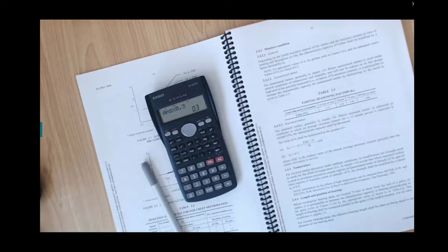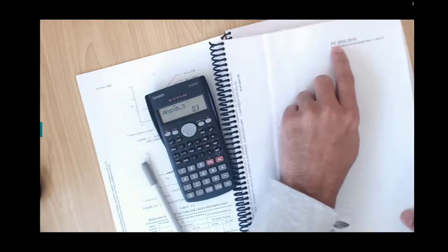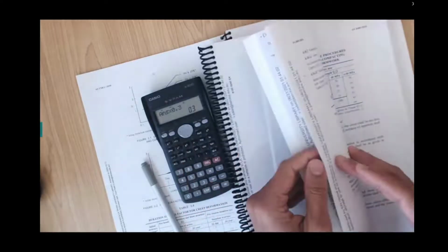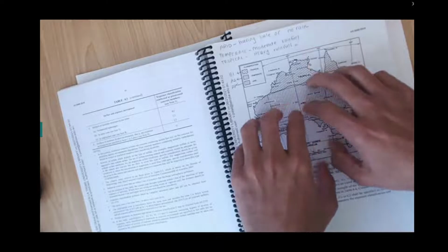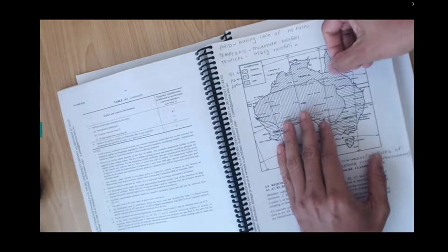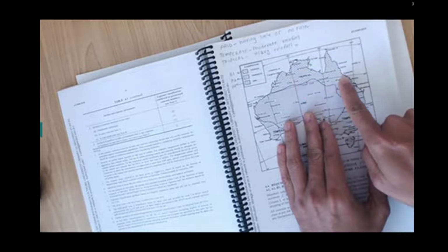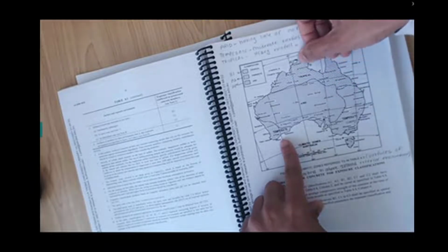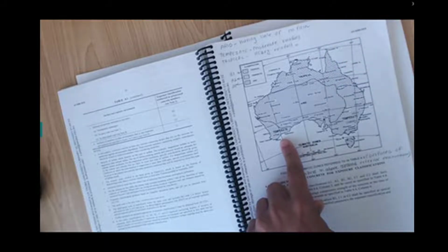But in case this is not the case, look, this is for your explanation only, because this other standard, which is AS3600, has given you these figures there. Probably next year we're going to teach you this one, but you don't need to worry about it. This is just for your information. The Bureau of Meteorology has given the rainfalls for all Australia, and the standards recognize that. If your timber is sitting in this hatched diagonal line area, which is classified as a tropical region, tropical regions meaning heavy rainfall, like Queensland and these Darwin portions here, then if you are designing your timber in this region, you would need to take K6 equal to 0.9.